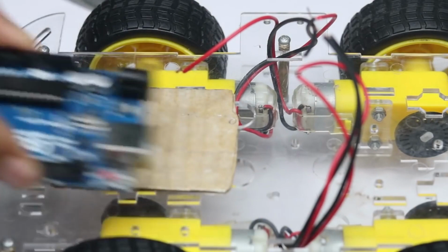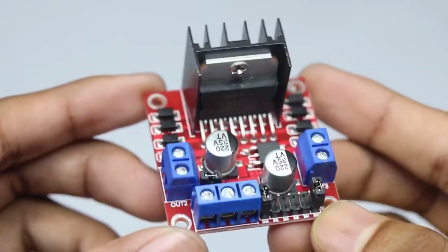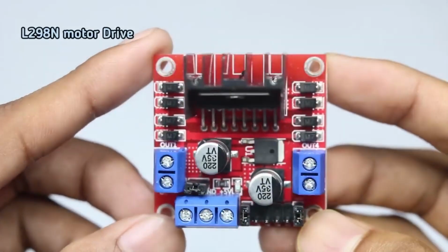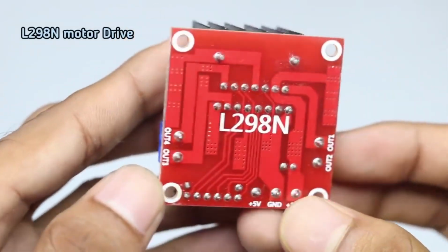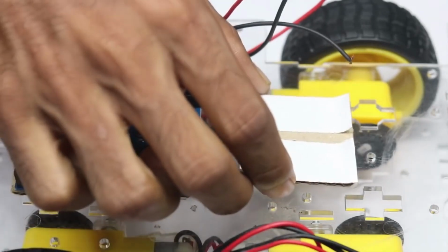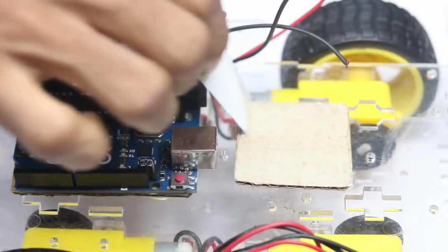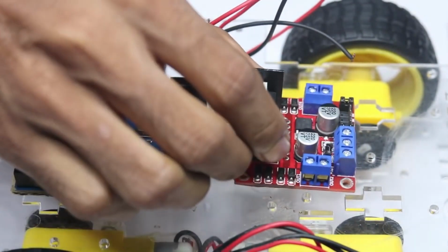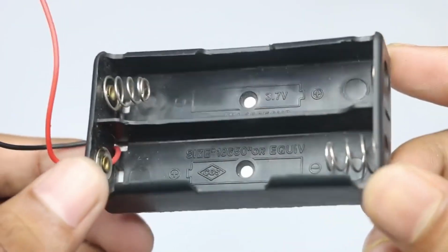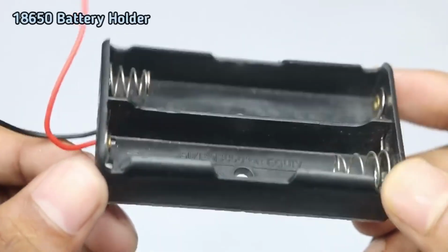The H-bridge motor driver is connected to the Arduino's input-output pins. Through the Arduino code and the H-bridge, the motor speeds are adjusted. The speed of a DC motor can be regulated by adjusting the input voltage, with one of the most prevalent techniques being the use of pulse width modulation. Pulse width modulation involves modulating the average voltage delivered to an electronic device by rapidly toggling the power on and off.